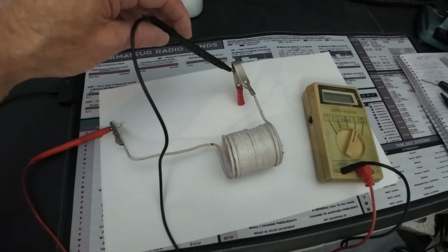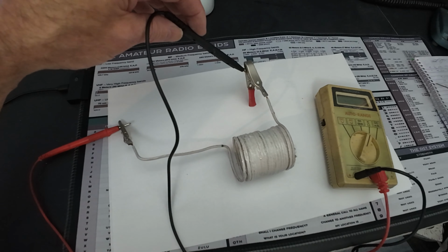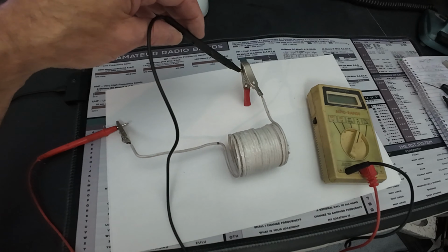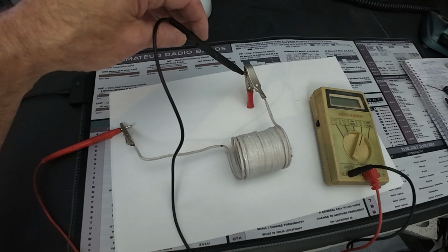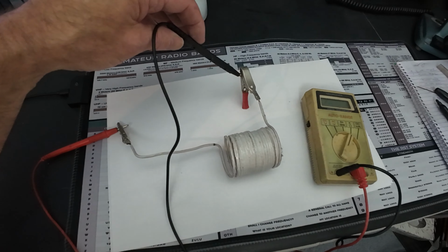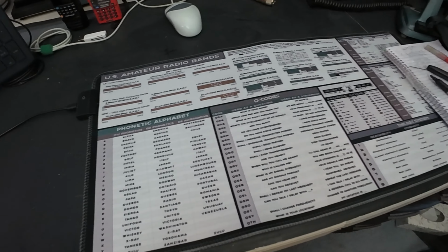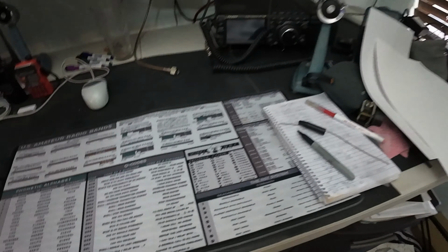With inductance, it's just the opposite. We have voltage right away, but we don't have current. It takes an amount of time for the current to ramp up in the circuit. So current lags voltage by a certain amount. In a purely inductive circuit, current lags voltage by 90 degrees. So interestingly, these two components work well together.